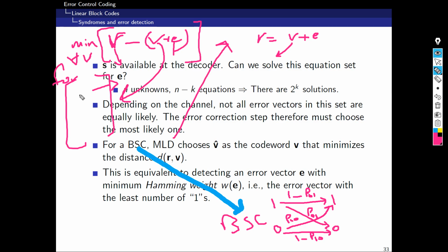And the one that gives you the minimum result here, that reduces this value to a minimum, you detect it as the code word that the transmitter used to represent the message. And from here you detect that this was the code word. This process of detection, we call it maximum likelihood.